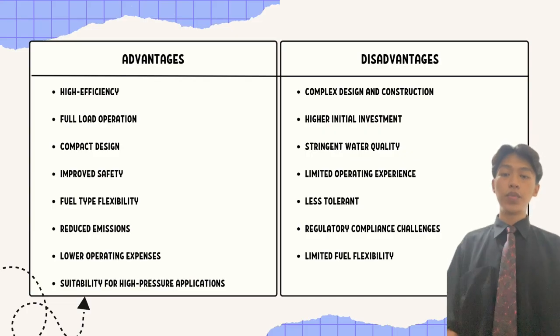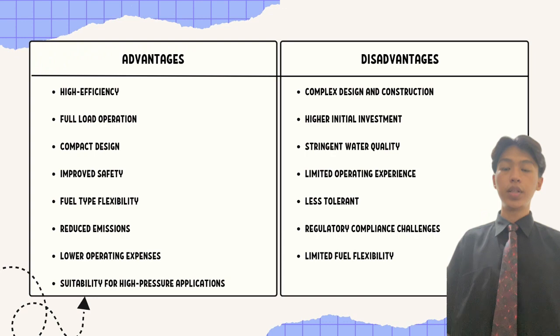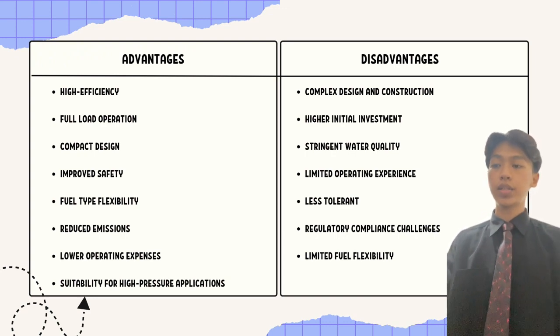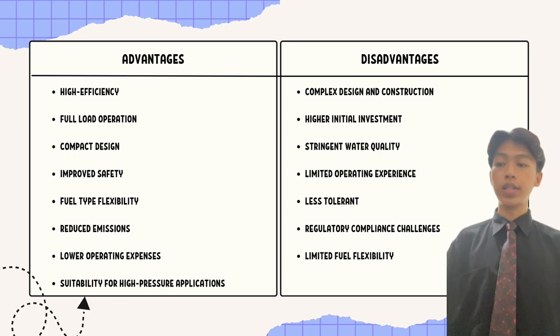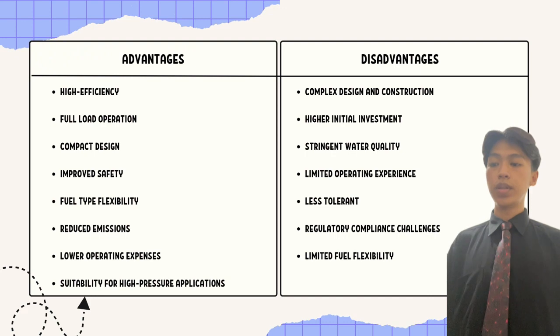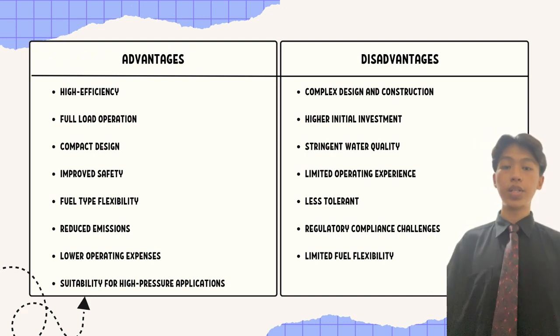So now let's move on to the advantage and disadvantage for Benson boiler. The advantage for Benson boiler is high efficiency, full load operation, compact design, improved safety, fuel type flexibility, reduced emissions, lower operating expenses, and suitable for high pressure application.